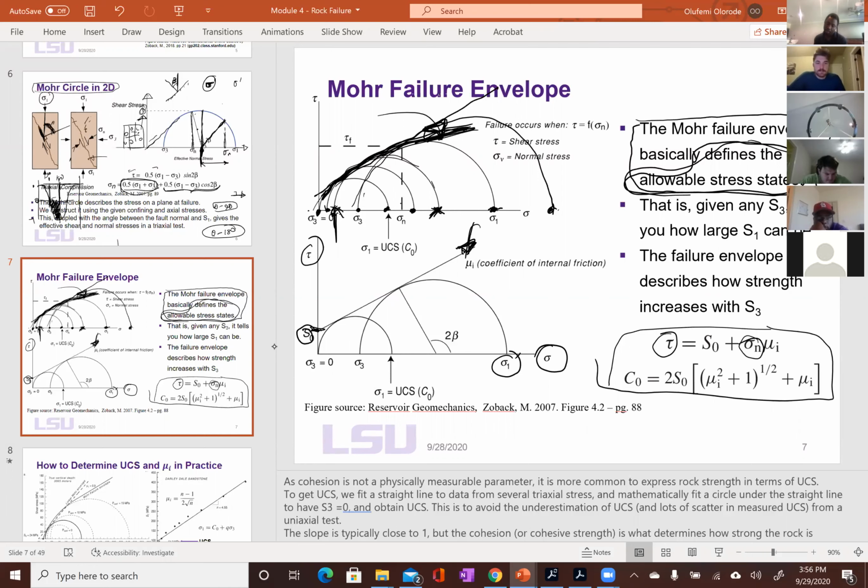And what is cohesion? What's the definition of that? It's the degree to which, what? To which the rock grains are held together. So for stronger and stiffer rocks, they will have a higher cohesion. So it's very important to know that the intercept you get from tau versus effective normal stress is cohesion.